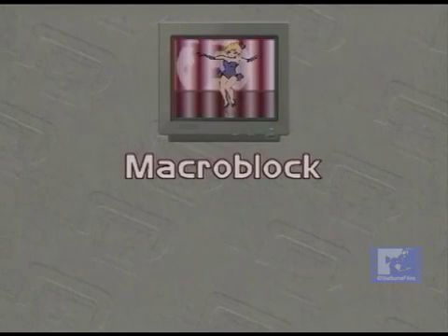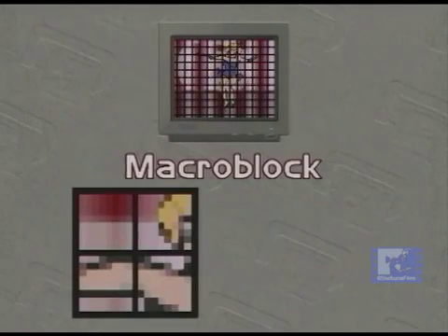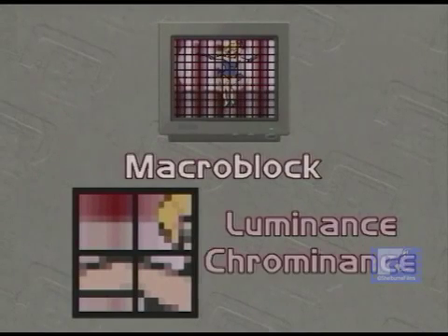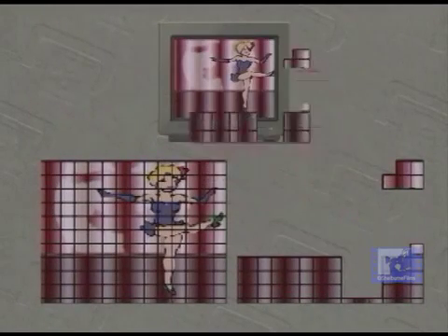Video sequences are highly correlated in time, with each frame in a sequence quite similar to both the preceding and following frames. It is therefore unnecessary to resend the parts of the image in which no elements have changed. The basic unit used for motion compensated prediction is called a macro block. A macro block consists of 4 8x8 blocks of pixels containing the luminance or brightness data and 2 corresponding 8x8 blocks of chrominance or color data. The encoder economizes on bandwidth by instructing the receiver to recall a previous frame's unchanged macro blocks from a buffer storage circuit and reinsert them into one or more subsequent frames. This requires substantially less information or bandwidth than sending all frames in their entirety.